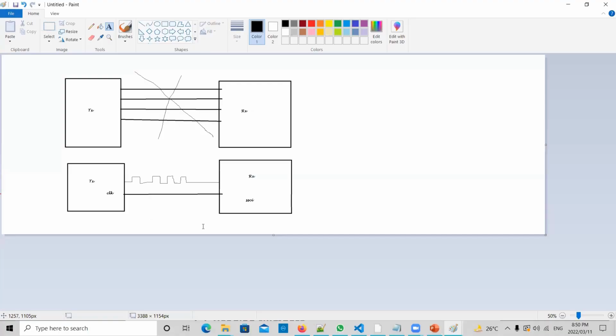When they want to transmit something to the receiver, they will initially notify the receiver, hey, I am going to send something. That is denoted via a single bit called start of frame. It is just like a jerk that you are producing in the communication link. The moment you produce that jerk, the receiver will come to know that something is going to happen. So that is called a start of frame.